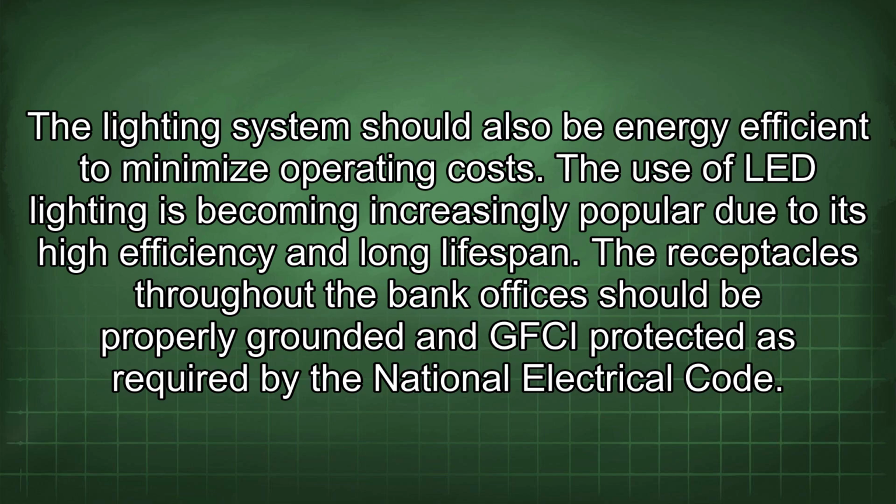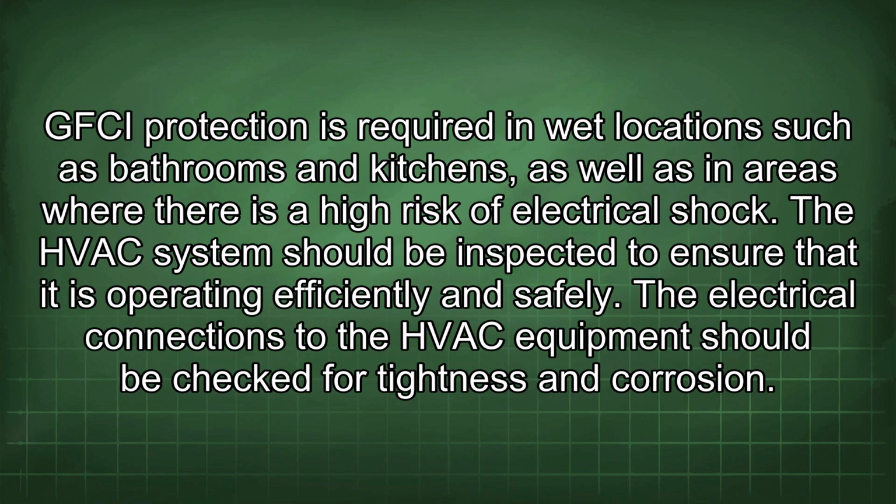The use of LED lighting is becoming increasingly popular due to its high efficiency and long lifespan. The receptacles throughout the bank offices should be properly grounded and GFCI protected as required by the National Electrical Code. GFCI protection is required in wet locations such as bathrooms and kitchens, as well as in areas where there is a high risk of electrical shock.